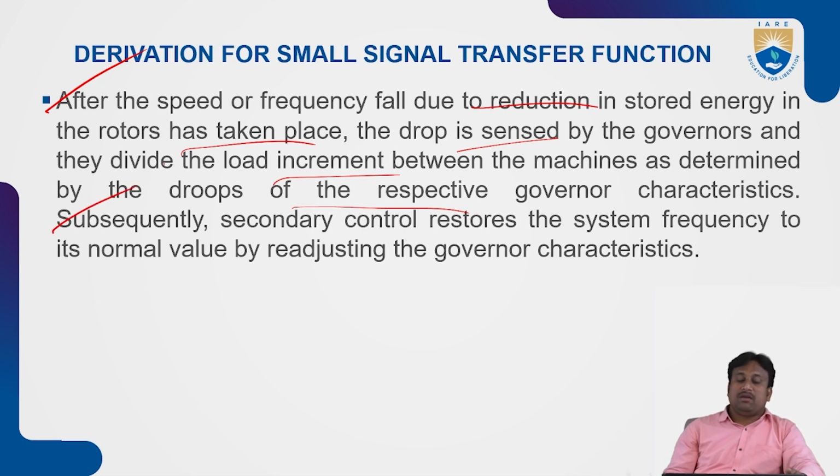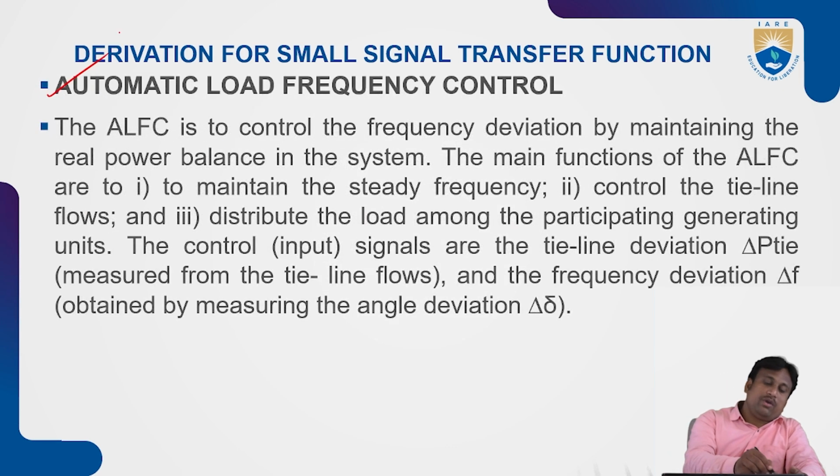So there will be subsequent secondary controls. They will restore the system frequency to its normal value by readjusting the governor mechanism characteristics. Here we are going to discuss one more parameter with automatic load frequency control.